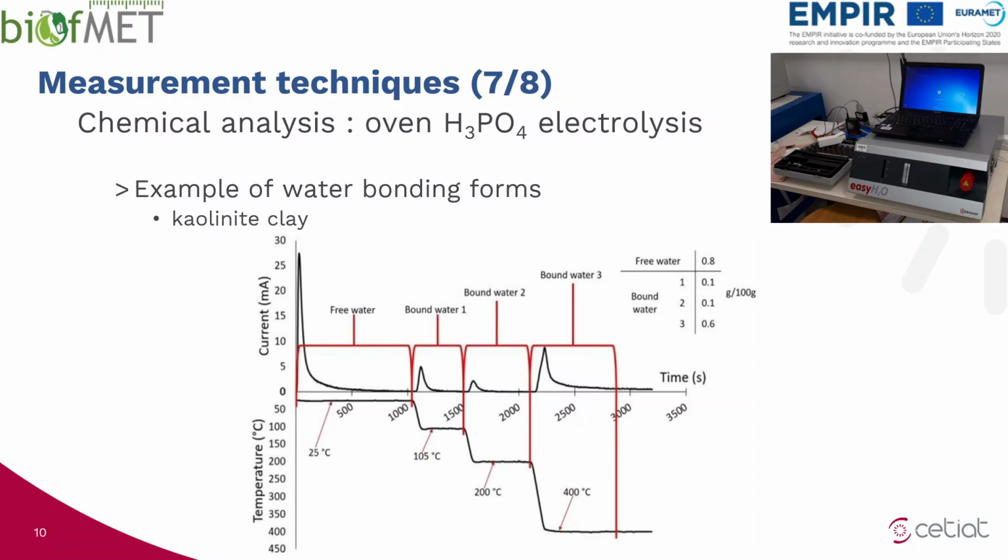As can be seen, 4 peaks are measured following the temperature profile, allowing for the identification of 4 types of water bonding forms: free water, the first bond water, the second bond water, and the third bond water, leading to the quantification of each bonding form.